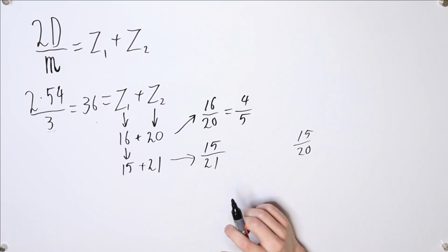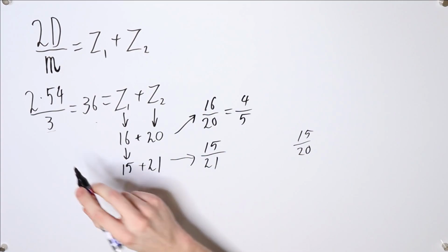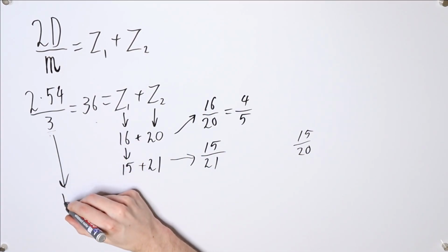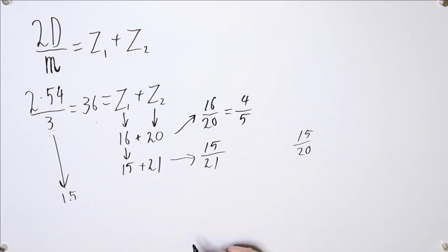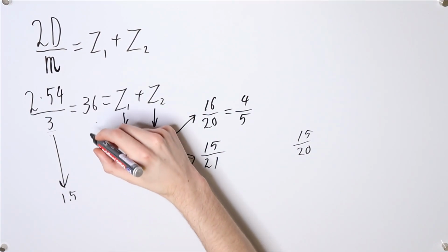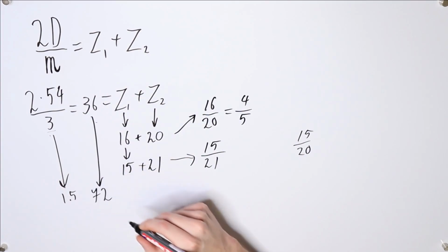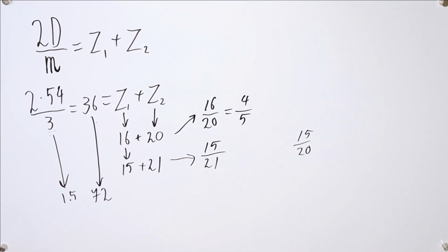Now, if you want a little bit more granularity in this, what you can do is take this module and divide that by 2, for example. So you choose a smaller module. And in that case, the total number of teeth is increased. And in that case, you have a little bit more flexibility in choosing what gear ratio you want.